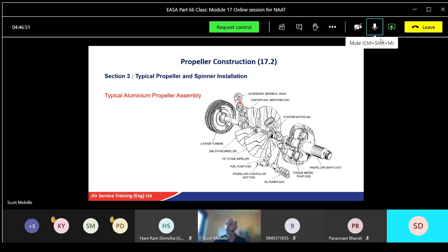Again, there'll be a reduced gearbox ratio. And this one's got starter motor shafts. There'll be a starter connected to this bit through a bevel gear, which will rotate the shaft. And then we come to the reduction gear housing for the propeller, which will also have the torque meter. Members spoke about the torque meter systems yesterday, the hydromechanical and the electrical, and this is the hydromechanical one, just an example.